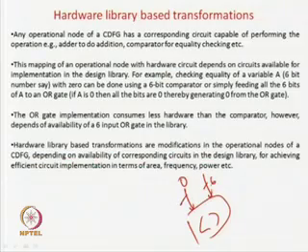For example, if I want to compare a 6-bit number with 0, how can you do that? You can use a comparator. It is very simple. This is your number 0, and this is the 6-bit number which you are taking, and these are all 6-bit zeros. If it is all zeros, then you get the answer as 1, and so forth.